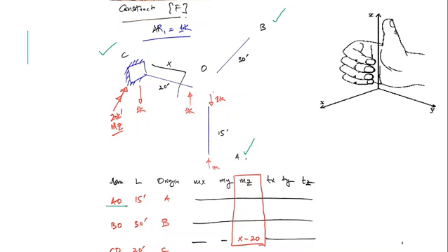So the origin for AO is A, so I'll start from here. This distance would be Y. I have to find all moments here. Now you have to see all the loading below that section, because the section has started from it. So all the moments that are being formed here would be taken into account. This is 1 kip in Y direction, and this member is in Y direction, so there would be no moment. As a result, all these boxes are empty.